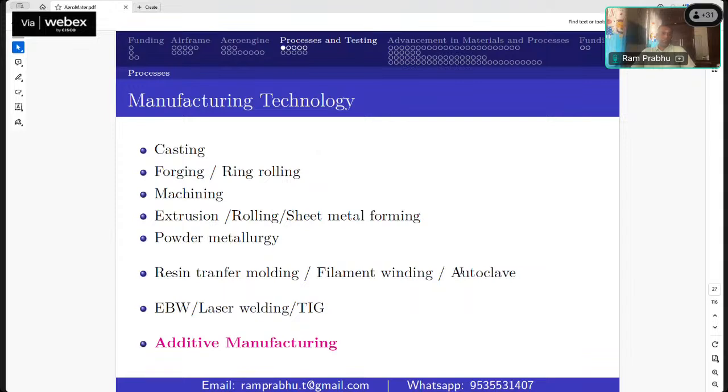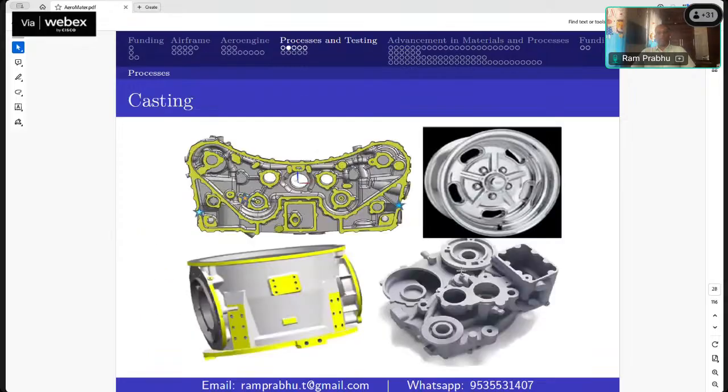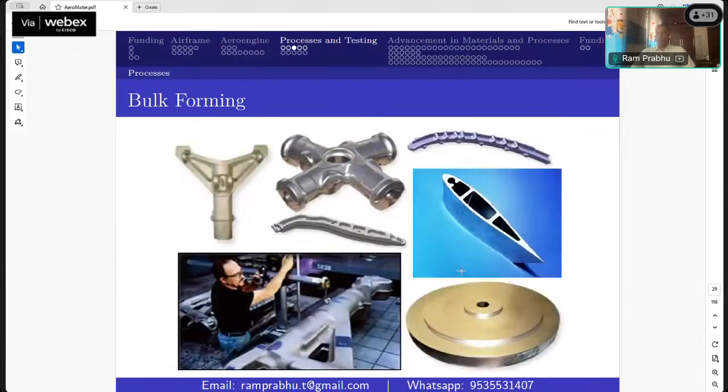We don't use any polymer additive manufacturing because there are no standalone polymer parts in the aircraft. Just to give an idea, when I have very massive parts with a very complex geometry like a helicopter gearbox or the aircraft gearbox, I opt for sand casting. When I have big parts, not of complex geometry, but which need strength, mainly fatigue properties, like a disc or the landing gear, I go for forging.